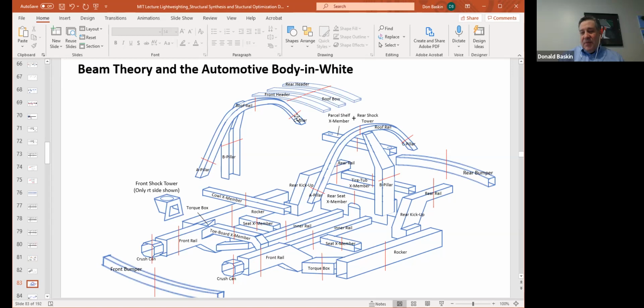Consequently, they will pay more money to put materials with higher strength to density or stiffness to density ratios higher up in the vehicle, or in the front of the vehicle, right? So that they can shift the big heavy engines up in the front. They want to shift the weight distribution rearward, right? So if you lighten up the front, that's one way to do it. So yeah, they'll use carbon fiber.